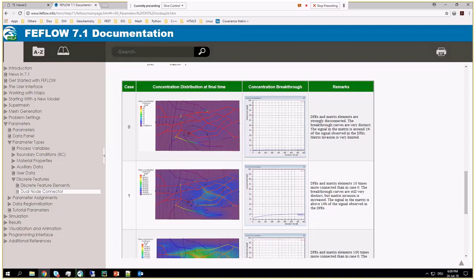But I was mainly talking in general, because you can take our solution, but you can also just go to any other provider like Amazon, for example, or Azure. They also offer high computational options. You need to install FEFLOW, and FIPS can work in this, and you can have parallelization. We have done multiple projects with cloud parallelization for mining cases, and it's quite convenient because the prices are not that bad. I think at that time it was about $3-4 per hour, for one of the most powerful solutions. In all cases, you need to have a FEFLOW corporate license because you need to share the license between the multiple instances.